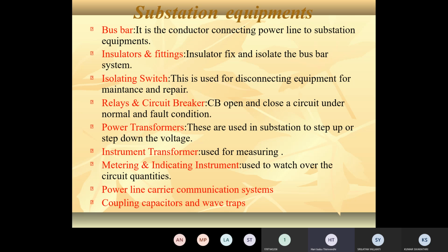The relay circuit is used with a circuit breaker, generally a bulk oil or minimum oil circuit breaker. Suppose voltages are less than 66 kV, we utilize a bulk oil circuit breaker. Suppose voltage is greater than 66 kV, we utilize a minimum oil circuit breaker, MOCB. MOCB is used for greater than 66 kV, whereas BOCB is used for less than 66 kV.